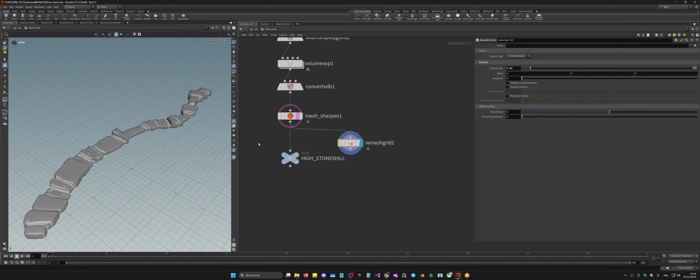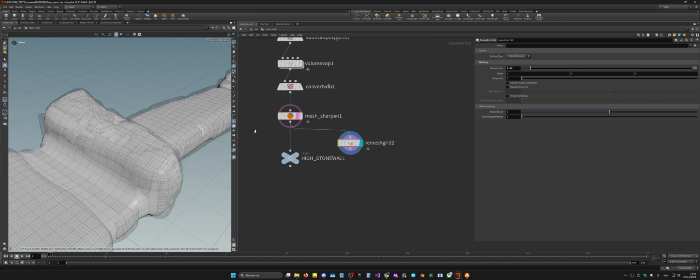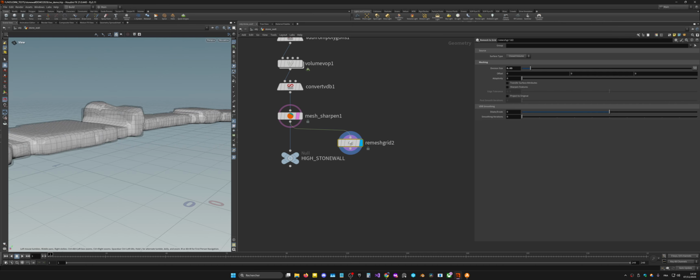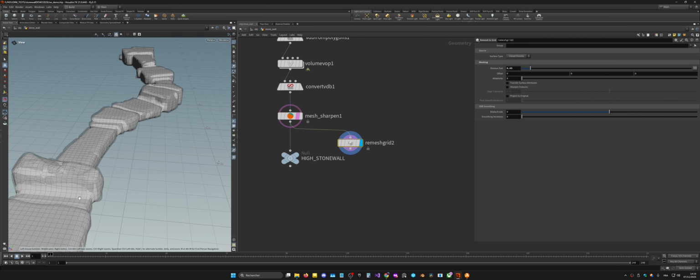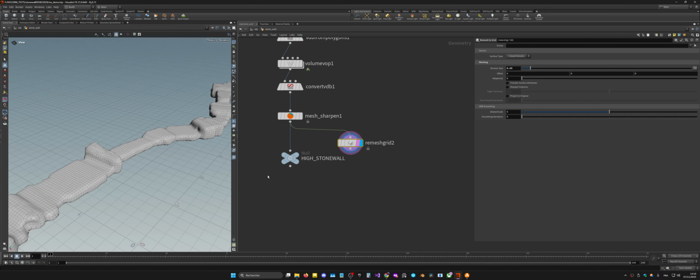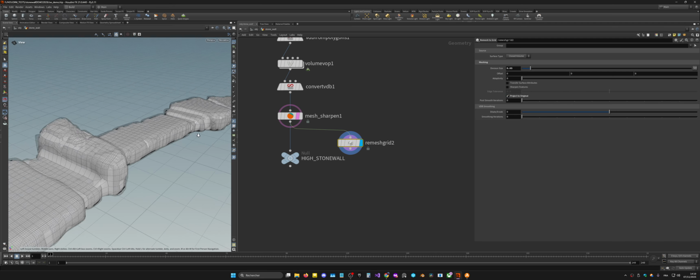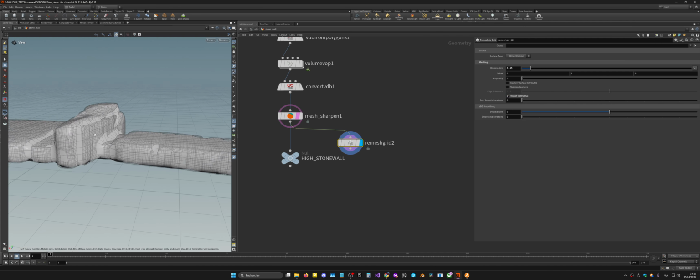So I will display the high res over. Alright, so now I have like a skin with less polygon. So this is the high, very high polygon. This is the low. As you can see, it's less polygon. When I generate this one, I use the project to original, that is recasting points on the eye surface. So the two surfaces are matching more.